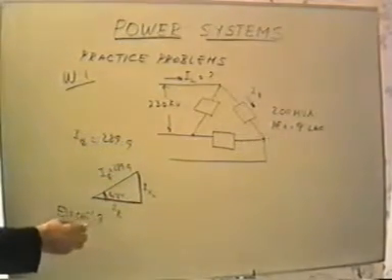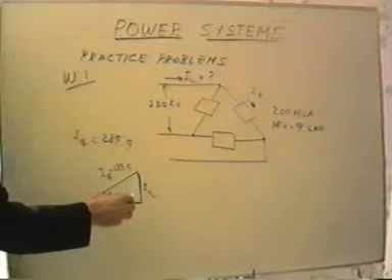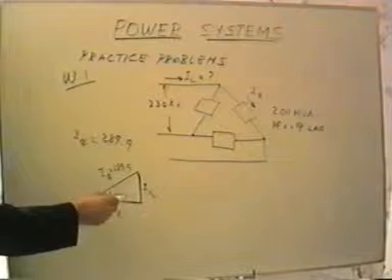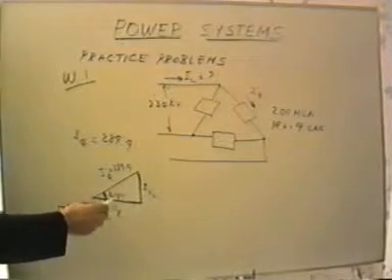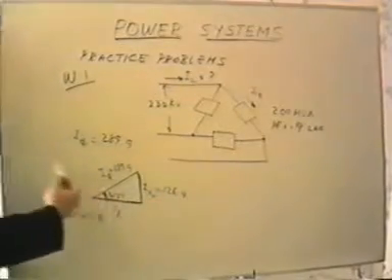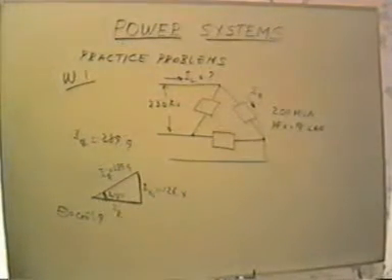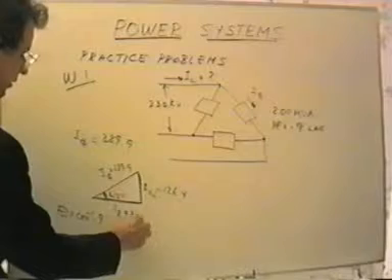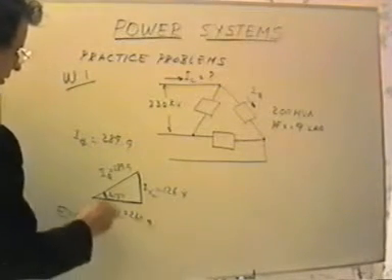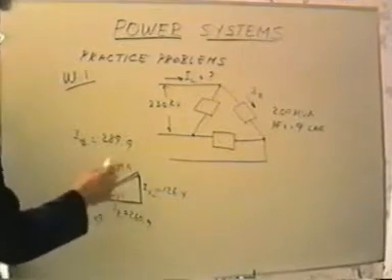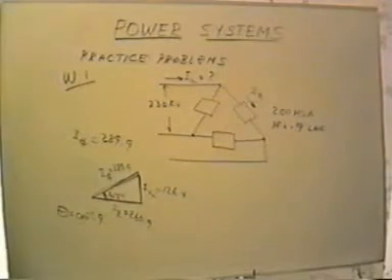And these two components respectively are, first, the component that's flowing through the inductive reactance, which would be equal to 126.4 amps, and the part that's in phase, the part that is real, is equal to 260.9, and these two, if you use Pythagoras' theorem, will give you 289.9 as the resultant.